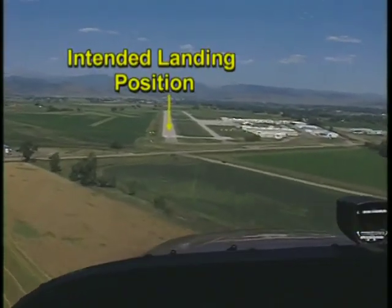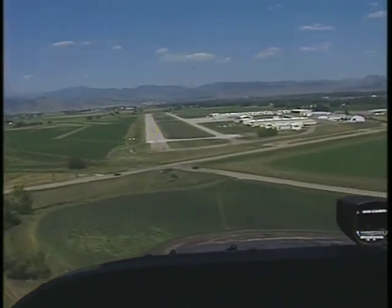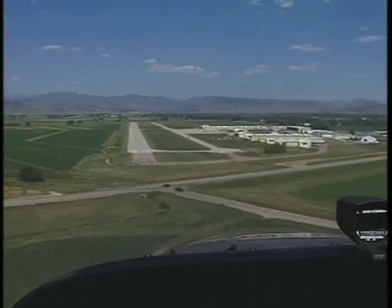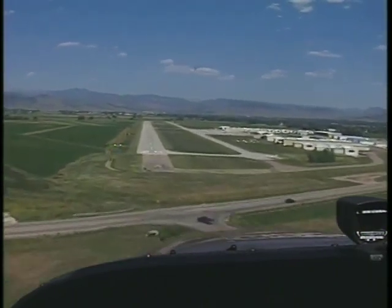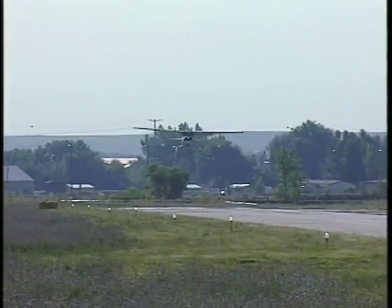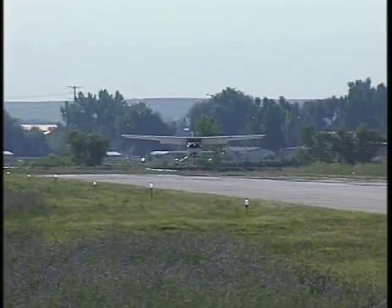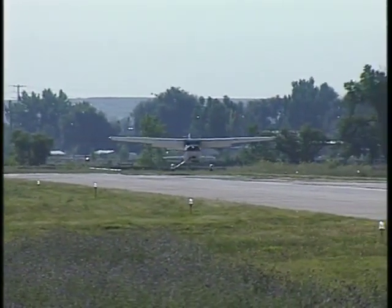While your goal is to touch down within 200 feet of the point on the runway, but not before it, with little float, do not attempt to stretch the glide or retract the flaps in order to make the landing point. Concentrate on making a safe landing, then re-evaluate your downwind and base locations and flap positions for the next power-off approach attempt.